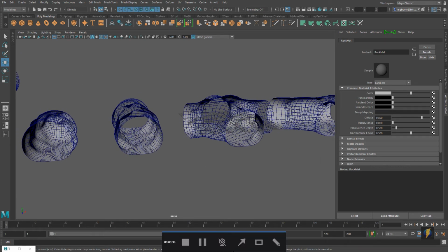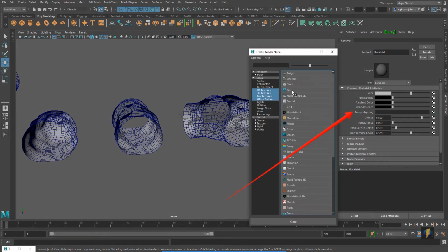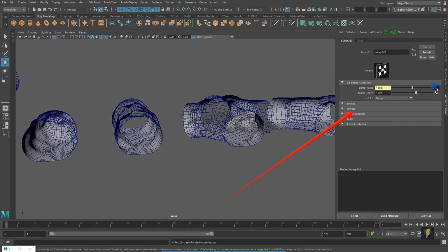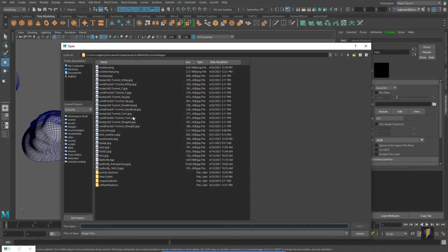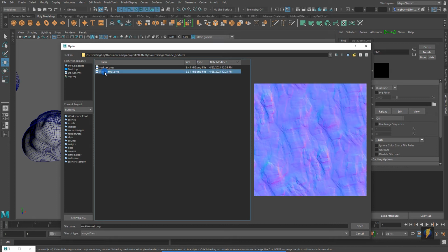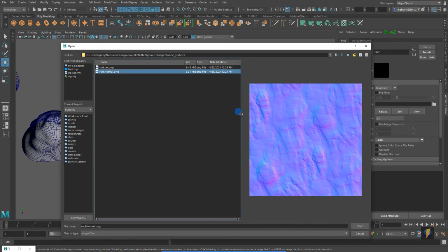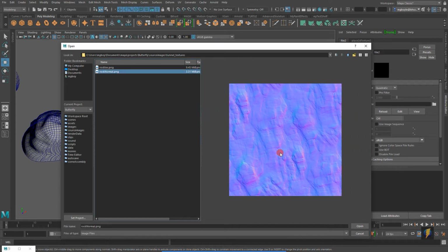So I will go to the bump map, click on the checkerboard, click on File, and we'll assign a texture that I've created for this purpose. Here is what it looks like. This is going to apply a normal map, which is a fancy kind of bump map. So we'll go ahead and apply that.